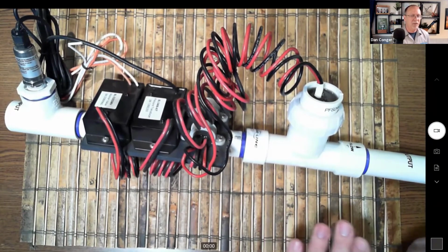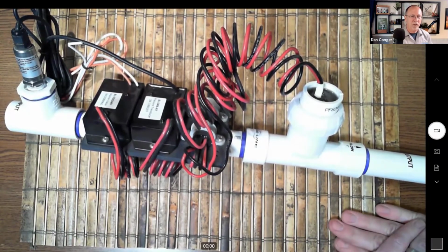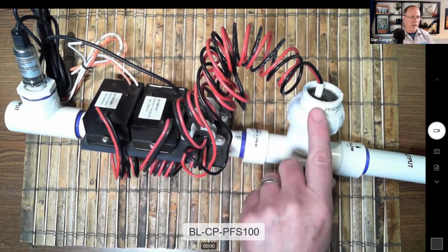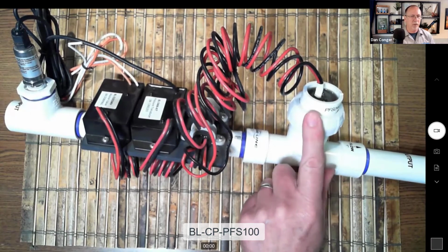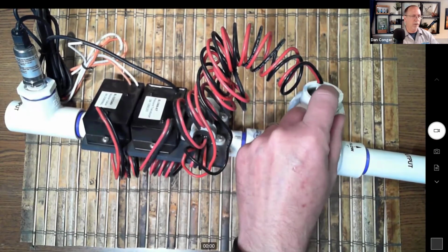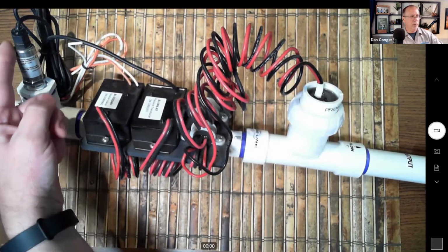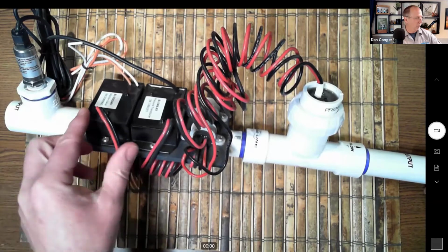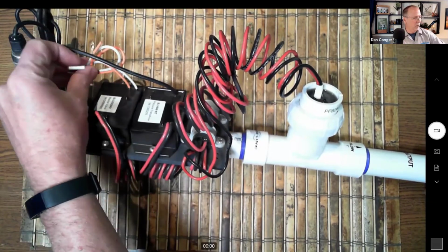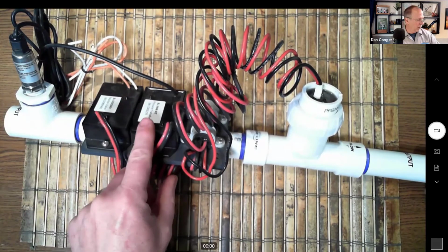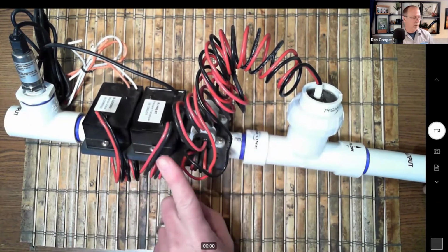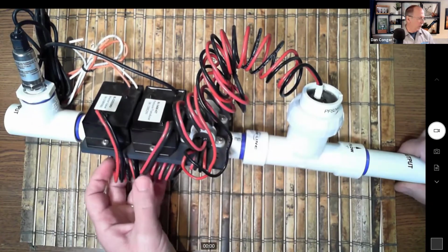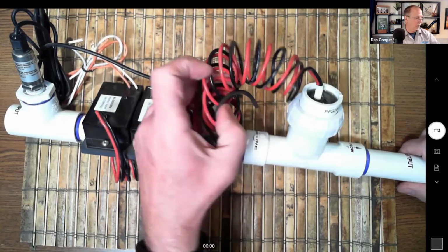I've got another device that can be used to measure flow, and this is a CP-PFS, control point PFS. So this has a plastic flow sensor in here, the same one that we saw before, that PFS with the built-in bicoder. Has a pressure transducer built in here, and then we've got a master valve bicoder. So we need to add our own master valve onto the leads here, and then we've got the pressure bicoder. So we've got a capability for pressure, flow, and master valve all together with one single 2-wire output, which is what we got right here.